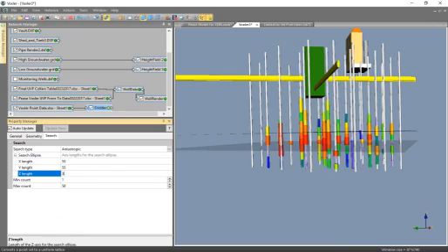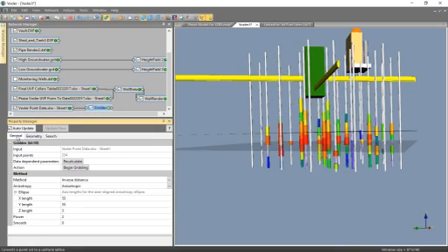Okay, and so both of these two settings work together. And so now that we have all the parameters set for the gridder, I can go down next to Action and click the Begin Gridding button. So Voxler's gridding the data. That was fast. Only took just a few seconds to grid the data.